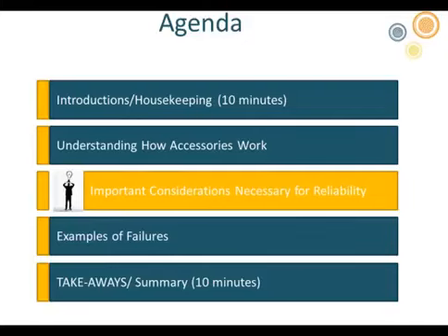So like I say, 10 mils is not very much, and that definitely caused a problem. And it's probably a less deep knife cut than that will cause issues. So that's why cable prep is so important to reliability and to long-term performance. So thank you.